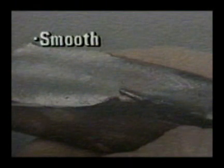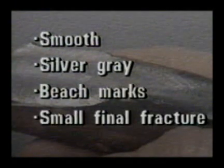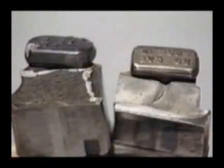Our list of characteristics should include smooth texture, silver gray color, closely spaced beach marks, and small final fracture, characteristics of high-cycle fatigue. Compare these two parts. Which is high-cycle fatigue and which is low-cycle fatigue?